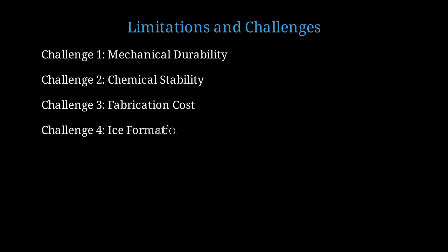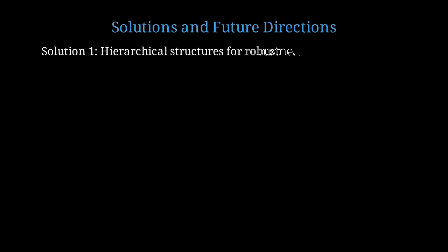Challenge 4 is ice formation. At low temperatures, water can freeze inside the nanostructure, irreversibly transitioning to a Wenzel-like state with high adhesion. But researchers are actively addressing these challenges with innovative solutions. Solution 1. Use hierarchical structures. The microscale features protect the nanoscale features from mechanical damage.